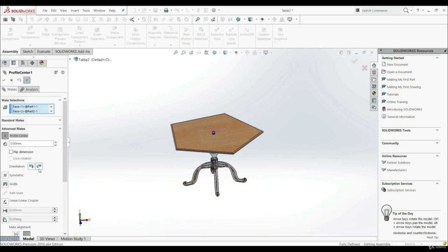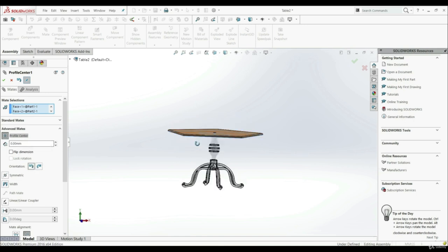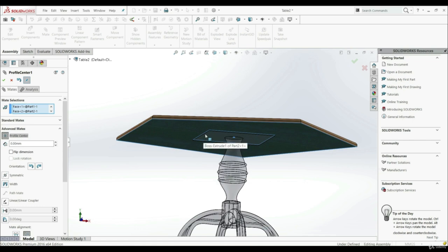the Orientation possibility. So we can go here to clockwise or counterclockwise. So if you click this, now can you rotate this plate? Like this. You can go to the other direction, like this. As well, here we have an option offset distance. Now we have a 0, so between those two faces the offset is 0.